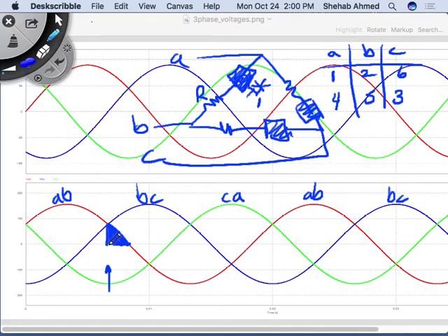If I maintain the same firing angle, then I will also fire the return. This is device 4, the return, the opposite polarity current. If I fire device 4 here, I get this voltage across my load. This is 1 and this is 4.